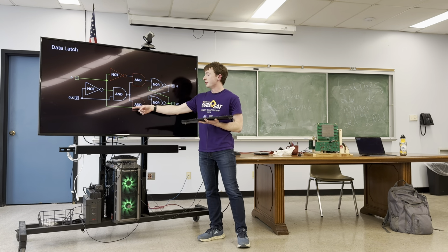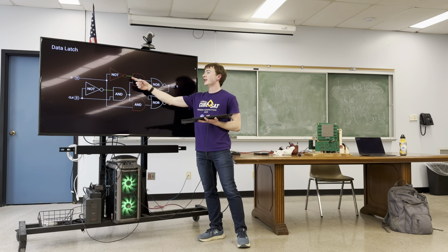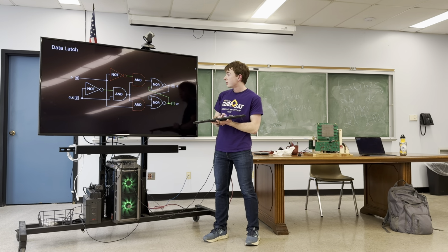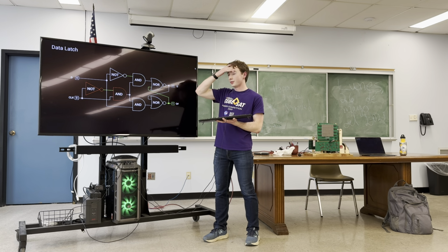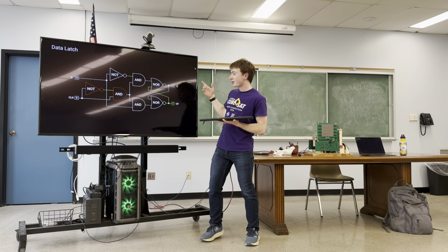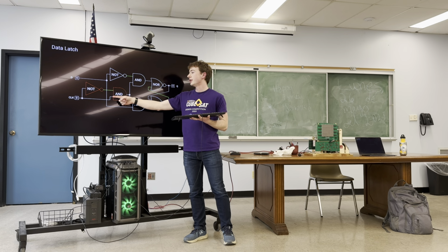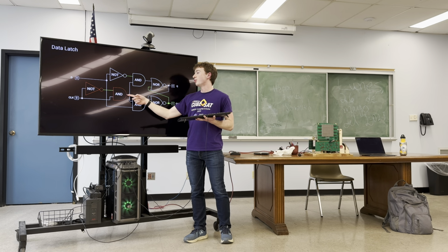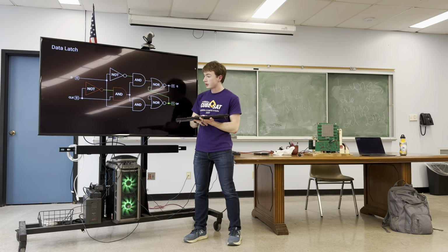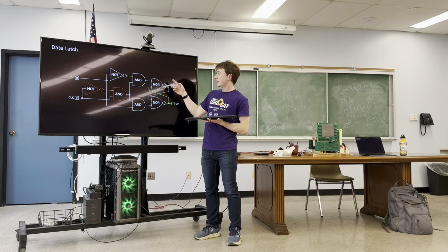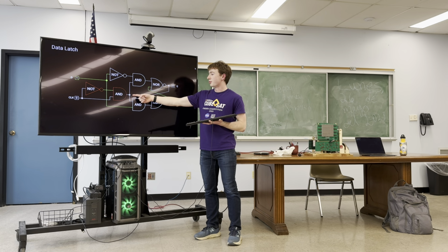Okay, so only one of these is ever on at one time because of the NOT gate and the data input there. Now this is the edge triggering, which is a little bit confusing because if one of these is on and one of them's off at all times, you think the output will never be able to be high or logic 1. But notice how this is on very briefly.